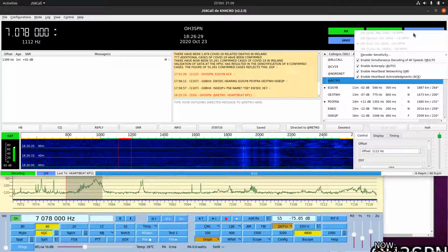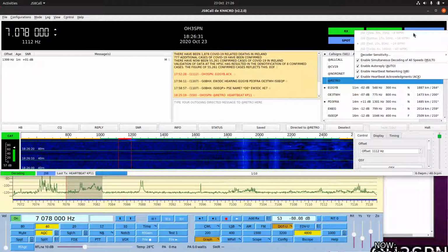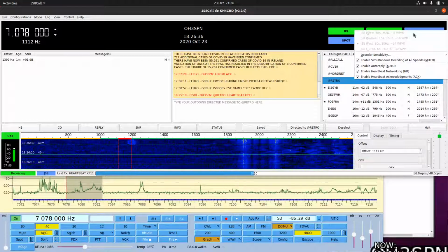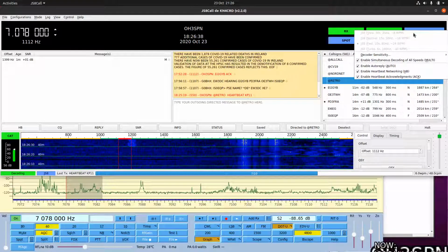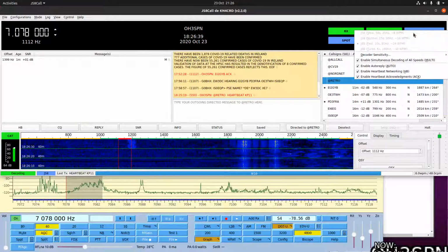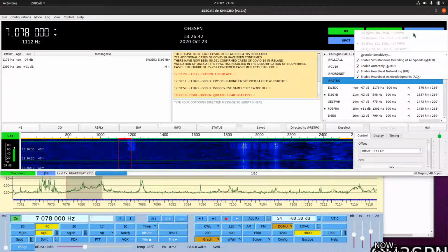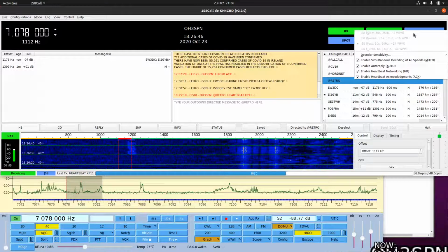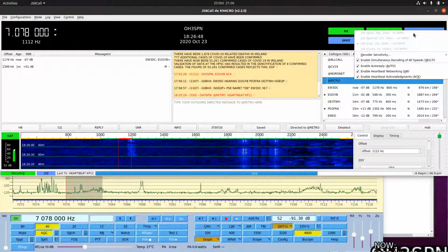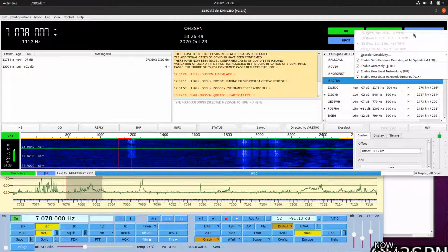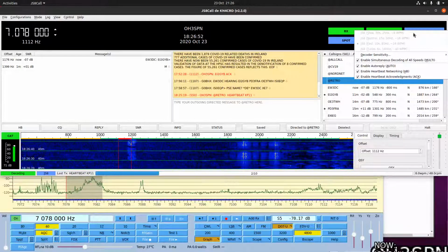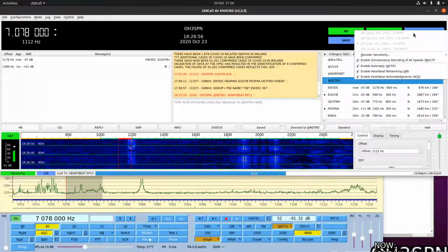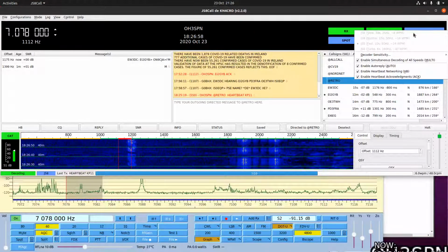So you set your audio level for whatever power you want in the middle of the passband. You then have a station calling right down the bottom of the passband. You try and call back, your transmit level is then out. So you may produce 20 watts when you're in the sweet spot, go right down low on the band, and suddenly you're producing 5 watts output, and you need to readjust your transmit levels to get the power back up to 20 watts at the extremities of the band.